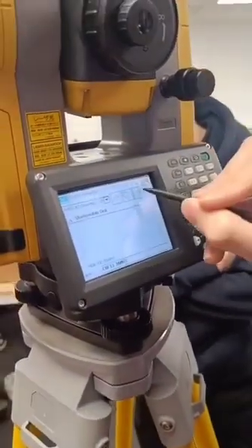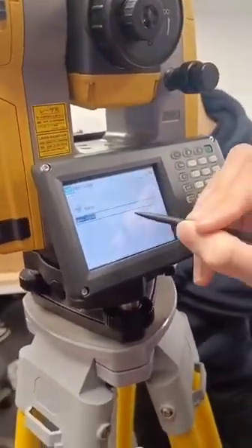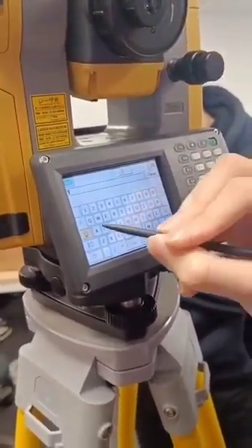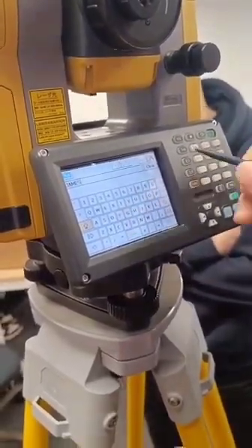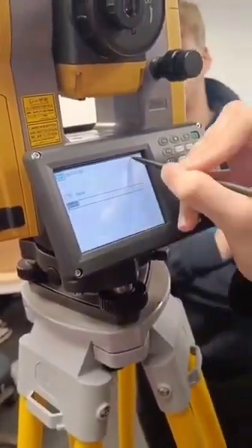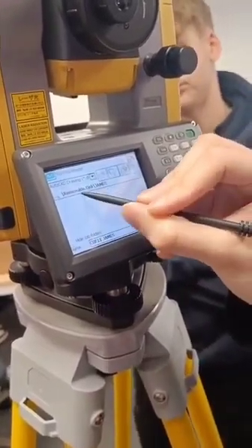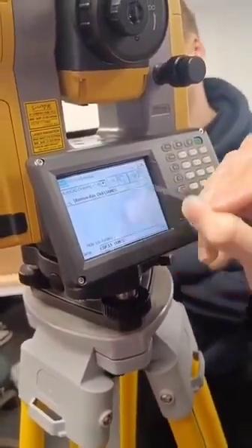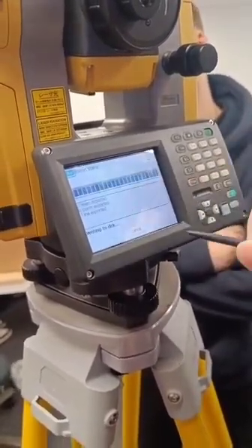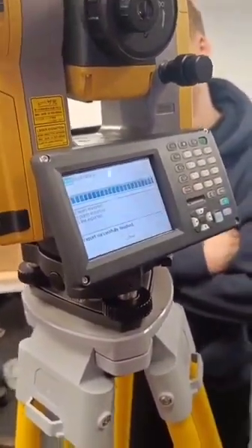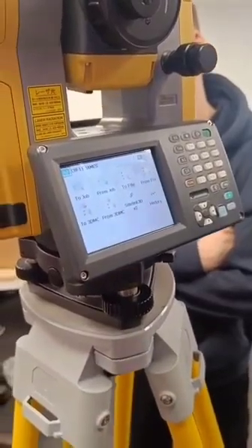You can create a folder for yourself. I'm going to do that. I'm just going to create a new folder, and I'm going to call it James, my name. When you're doing your exam, I will do the same, just to keep them all in the same place. So a new folder called James. There we go. I'm in there. You can see from the directory. And the name, I'm just going to keep it the same as the job name. Just going to hit next, hit the tick, and I'm just going to write it. There we go. That's the AutoCAD file exported.